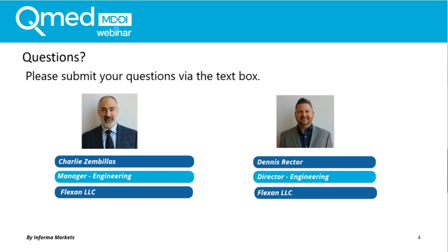All right, thank you, gentlemen. Another one has come in asking, does a multi-lumen tube require consistent wall thickness throughout? You'll generally achieve a consistent wall thickness. However, we will extrude to the specification that our customer has arrived at. So if the customer is calling for plus or minus 2 thousandths, our target would be plus or minus 2 thousandths, and we would monitor to that.